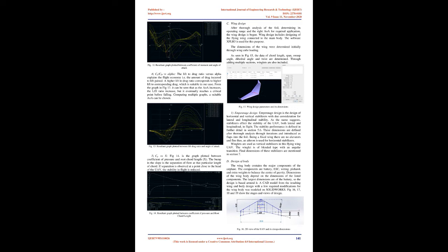The servo motor should be able to actuate with good responsiveness in air and should be able to overcome water pressure while it is underwater. The servo should also be completely waterproof. Keeping these considerations in mind, the Hitec Multiplex HS5646WP high voltage, high torque, programmable digital waterproof servo is chosen. 4 of these servos are used to actuate the 2 ailerons and the 2 spoilerons. Fig 2 shows the selected servo.